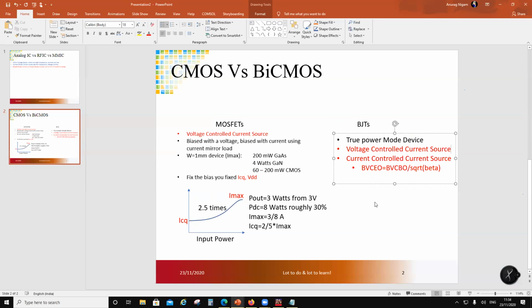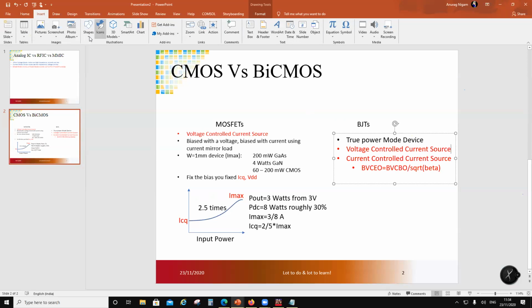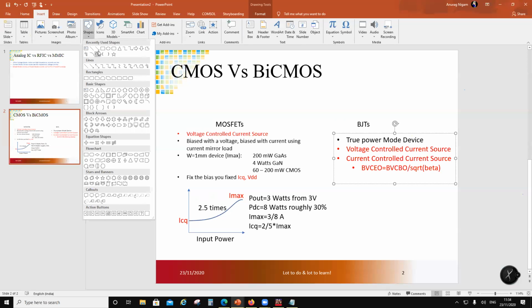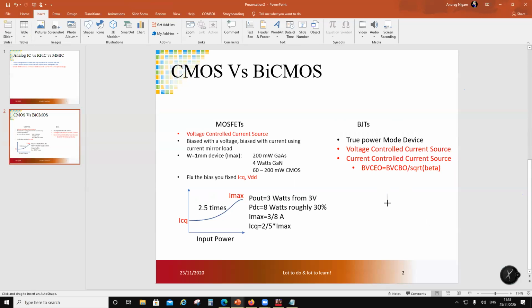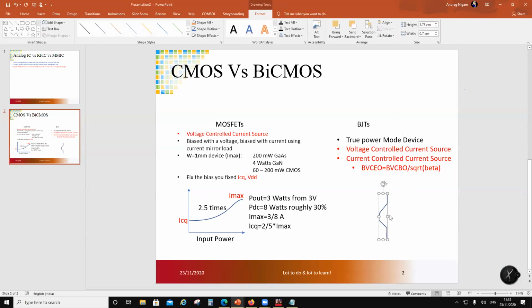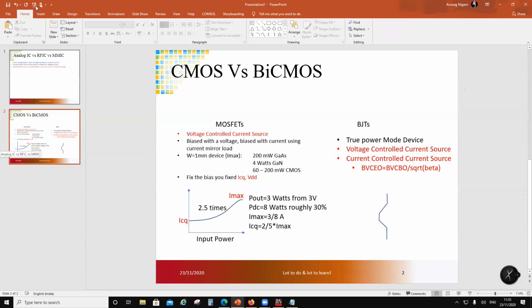What you do is you hang what you call a diode connected transistor on the base to the ground with a resistor, and you can turn on that device at any power level you want by scaling the resistor. So this is something which a book will not teach you. So let's say I bias it with a current and I put something like this. This is my transistor.